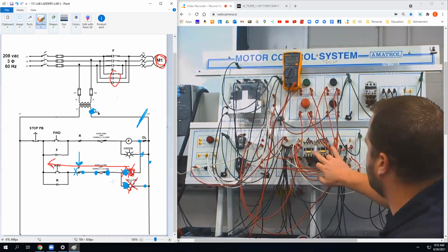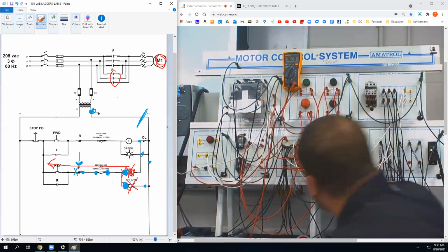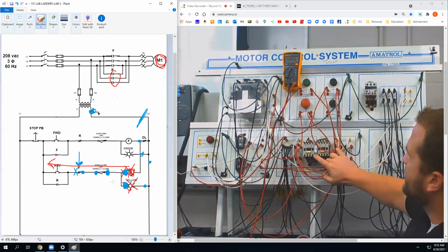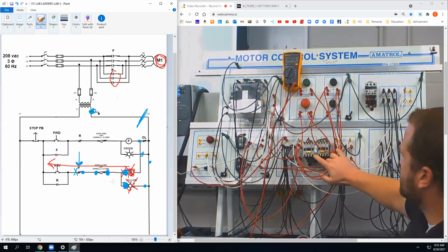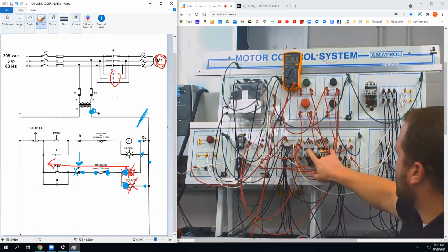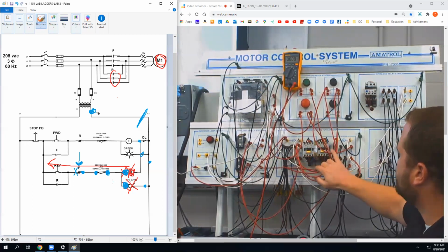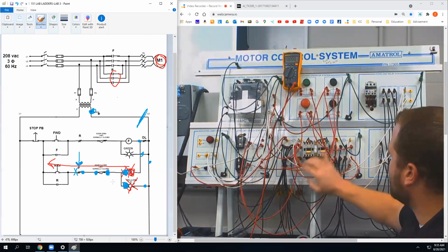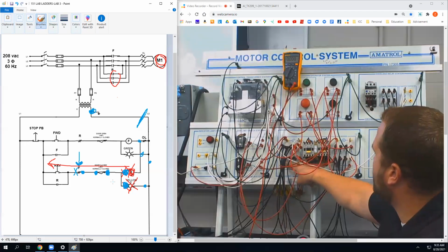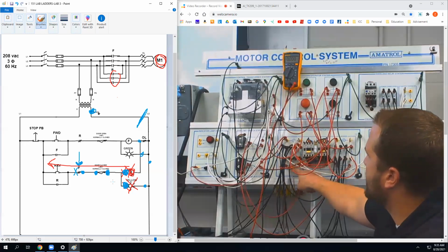This is a normally closed contact. There's a screw on top and a screw back here, with a wire going to it and underneath it. This is the interlock, a normally closed auxiliary contact attached to this coil. When that goes in, this should open up. When it's out, it should be closed, but I just found no voltage here and voltage here. So I suspect that this is actually open.